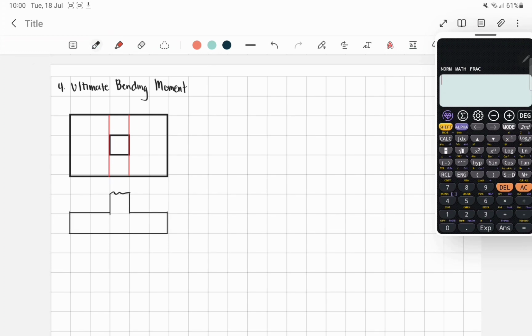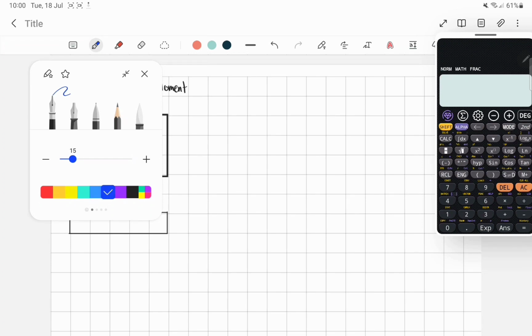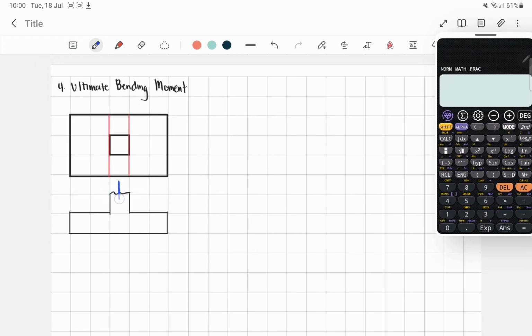Again, we have a force from our column acting downward, and from the ground a reaction pushing back, which is what we call QU. The assumption here is that our footing will act as a beam that is fixed at the critical section. This is our critical section.